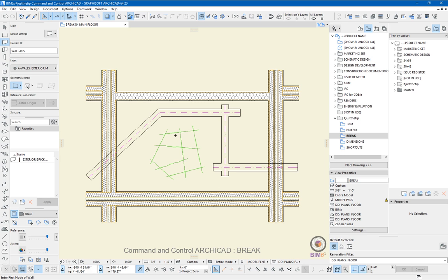If I want to change the colour of the line in here maybe, select this one line, it's one piece right now, but I can control click here, and you'll see a deliberate mistake because I'm not on the line tool, so I've actually just trimmed. So one of the next things we're going to talk about is shortcuts. We'll come on to that, but I'm going to use one right now, which is Ctrl Z for undo. Obviously that was a deliberate mistake. I'll grab the line tool this time. Now I'll select the line that I want to break, and I'll control click again, and because I'm on the line tool, this time I get a break.